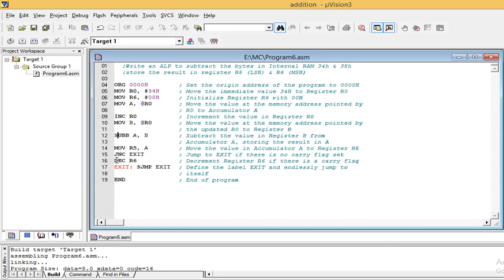The decrement instruction always reduces the value by 1. For example, if R6 is 34, the value will be reduced by only one and become 33. Subtraction is used for subtracting one value from another, while decrement reduces the value at that particular pointer by one. You can learn that while doing the execution.